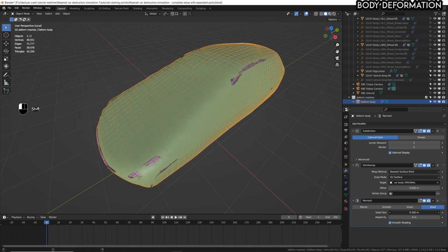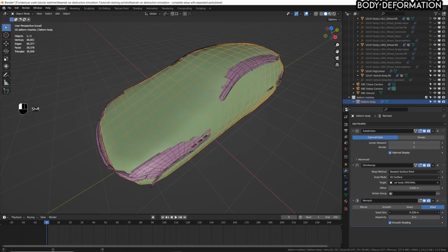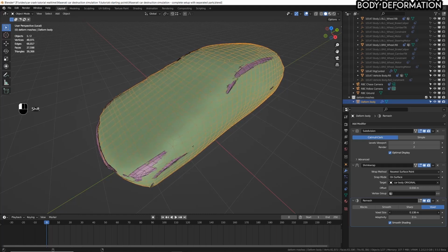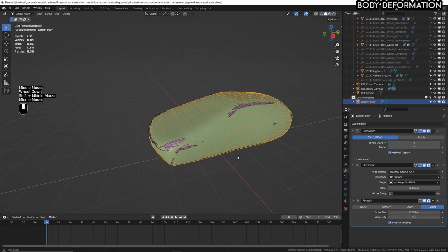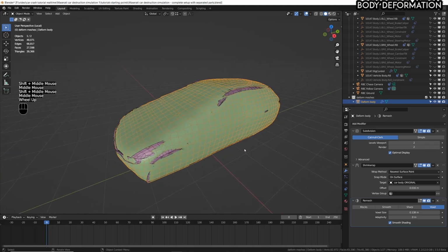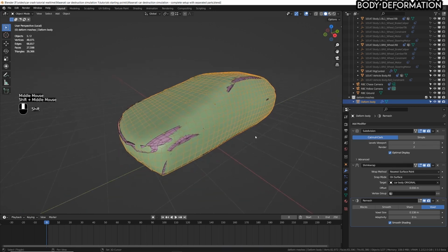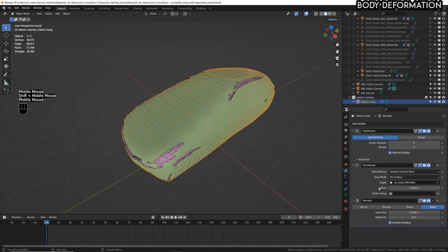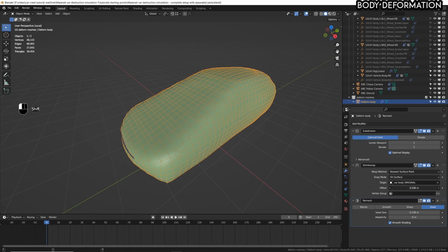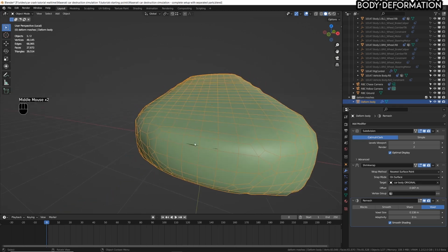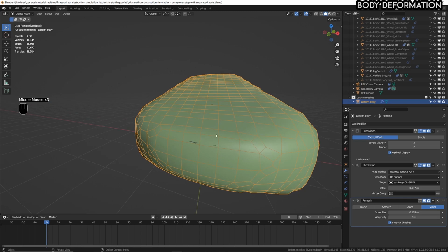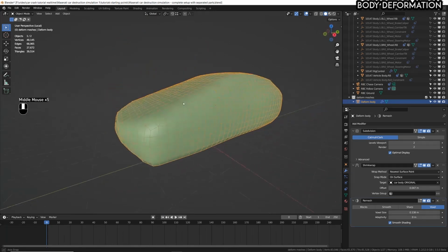And by the way, later we are going to need to check the total amount of vertices that we are creating for just this mesh. My goal is to have something around 2000 vertices, and if I remember well, a density like this should be 2000. By the way, we cannot check it right now because we need to apply these modifiers, but for now let's just not worry, let's save. So after this remeshing, we need to adjust by consequence the offset of the shrink wrap. So just a little bit holding shift so that you have precise control over the increments. Yeah, we have some little parts like this left outside. Don't worry about them. We are going to adjust them later using another system. For now, this is okay.